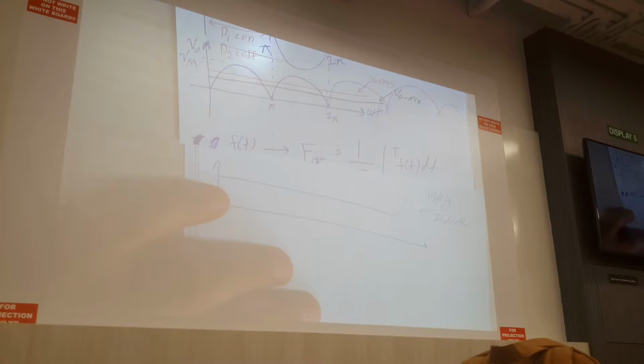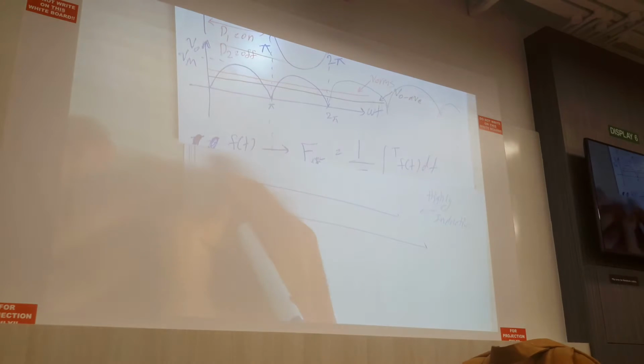So, whatever you need to draw in the exam or quiz is this fixed current. You don't need to draw the transient, but I just explained what will happen. So this will be IO, and the amplitude I put as IM, whatever the amplitude is. So for a highly inductive load, the current will become a constant value.